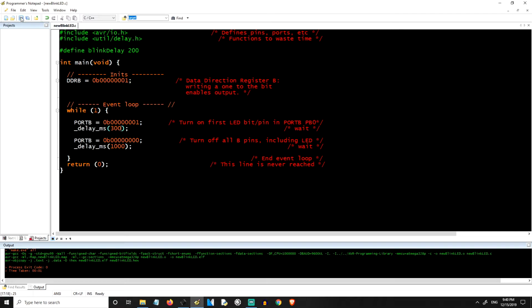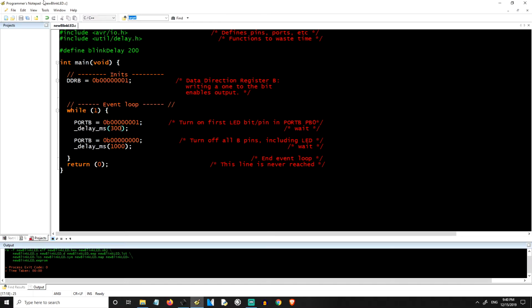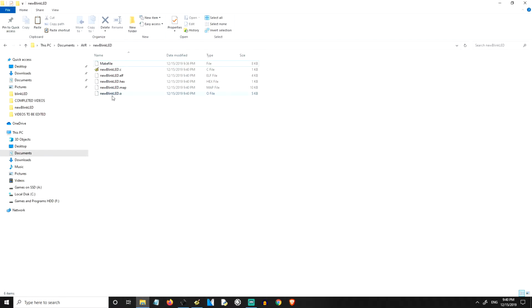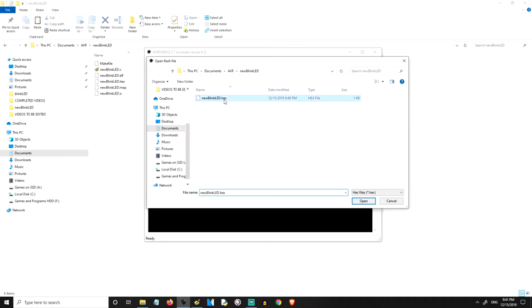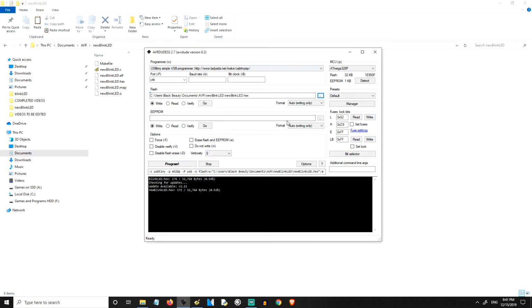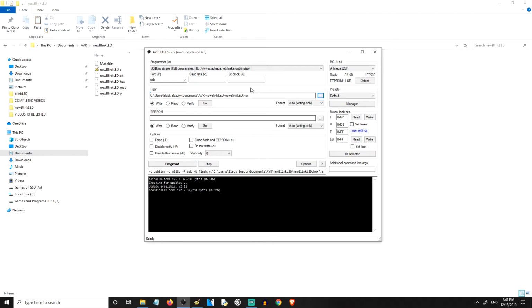Okay, you save your file, you go into Tools, and you make clean. Make clean is going to erase all those files. See how they just disappeared? Because you need to generate new files to accompany the updates to the program that you just made. And then you just click Make All. I do this a lot, so you really need to know about this. And if we go back to the file, boom, there they are. And you don't need to retype, you don't need to find the file again. It's the same file. It's still looking at that same direction, but I just do it for good practice. Just double click on the new file, although it's the same name.